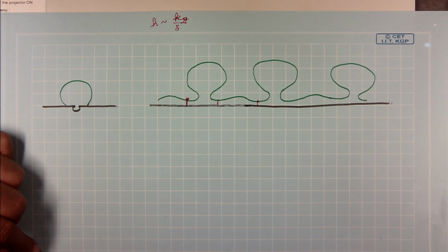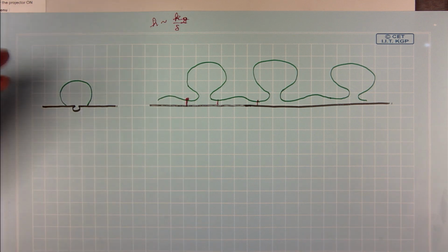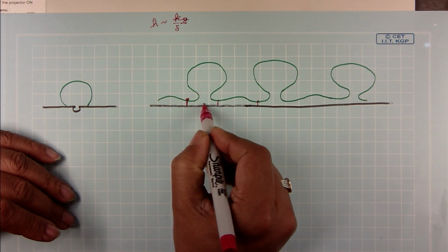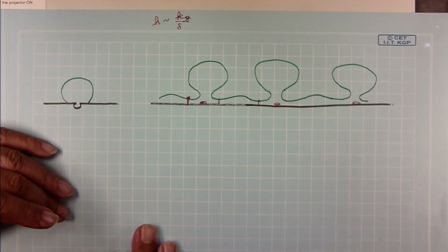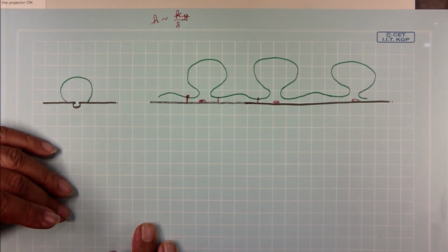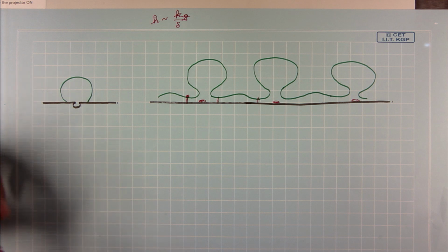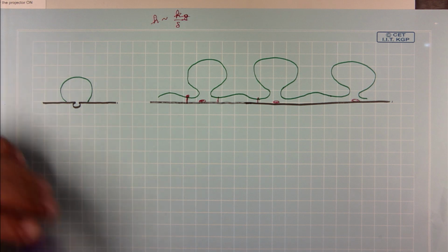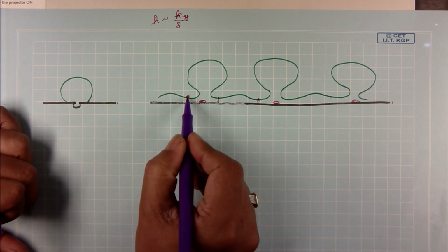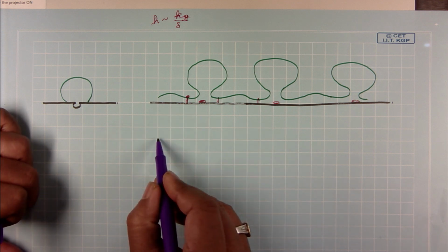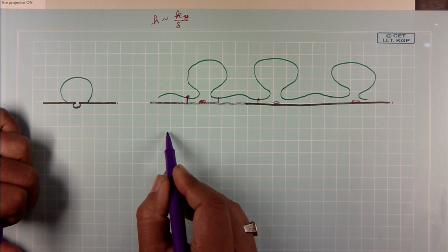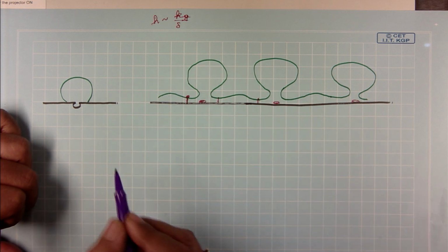Because the amount of path that the heat has to travel through is much longer, and therefore, virtually the area under the bubble is insulated. These places are almost insulated boundaries, essentially an insulation boundary condition. So, if I plot the heat transfer coefficient, how would it look? Well, your delta T is constant, is not it? It is always T_W minus T_sat. So, if I plot the heat transfer coefficient, I will get the inverse profile of the bubble of the vapor film.